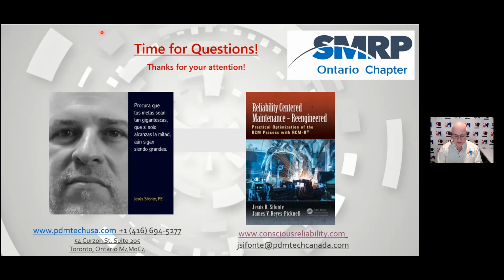So one of the contributions of the aviation industry when they started RCM back in the 60s and the 70s is that most failures related to rotating equipment, or any type of movement, could be a rotation movement or other type of movement, but dynamic equipment, most of the failures were random and also premature. So there is no clear relationship between age and failure probability.